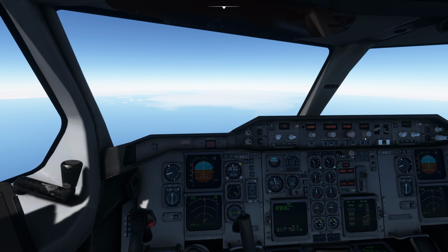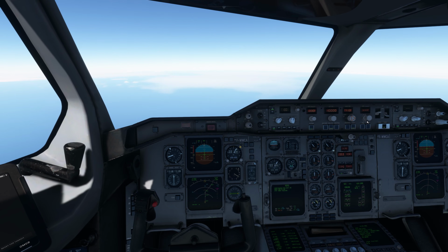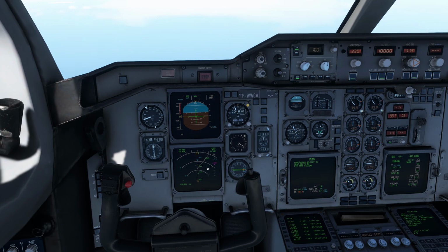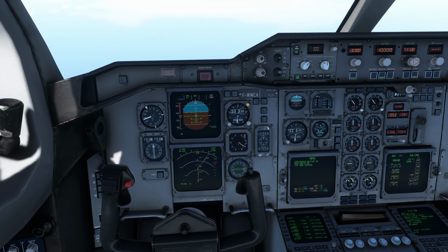And if you switch to the vertical speed mode, then the priority is given to the vertical speed rather than the speed. It's better to descend using the level change or the vertical speed mode, because what I've observed is that in the profile mode, the plane actually controls the speed before this point, but it is not at 10,000 feet at this point.